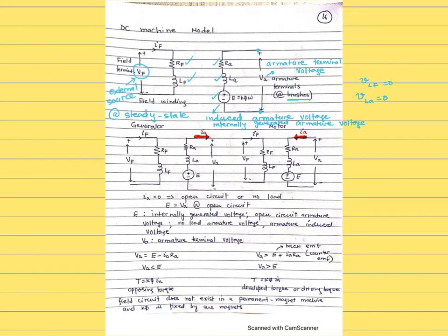Because the voltage across the inductor is given by L di over dt, one way. You also have the change in flux as well. So under steady state, this I is constant, which gives you di over dt equals 0, which gives you VL equals 0.